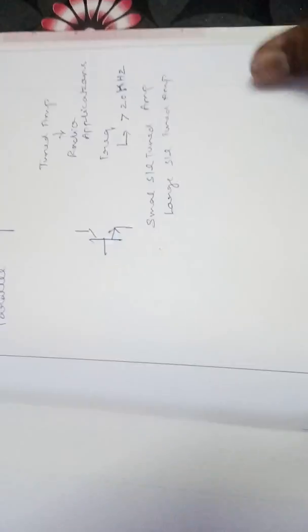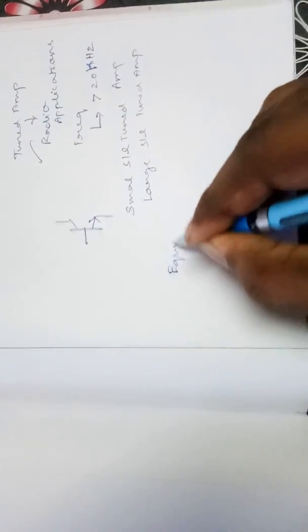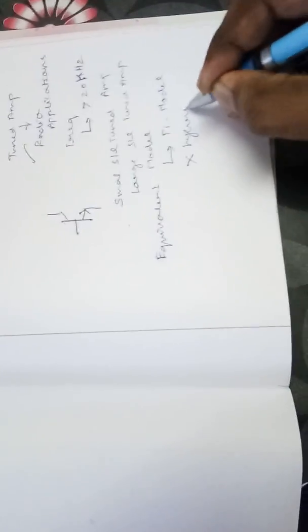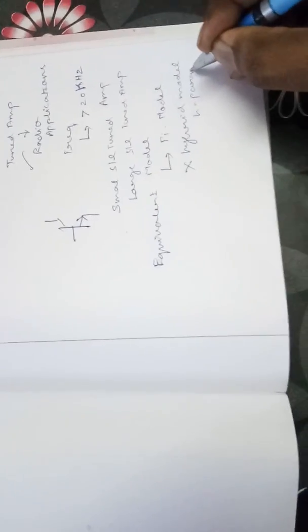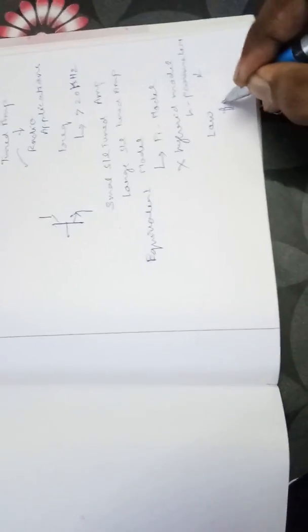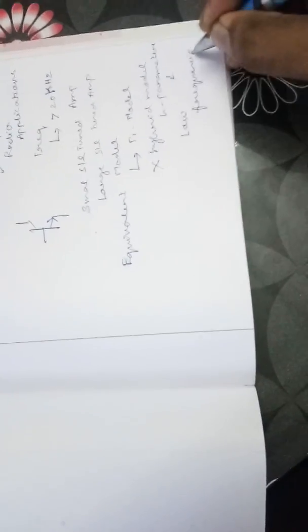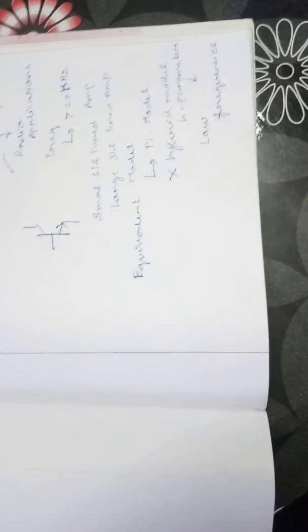Remember that whenever we are processing a radio frequency application, if we are constructing an equivalent model, that equivalent model should be represented in the form of a pi model, and it should not be in the form of a hybrid model. The reason why H parameters are not used is because H parameters support only low frequencies and are not applicable to high frequencies.